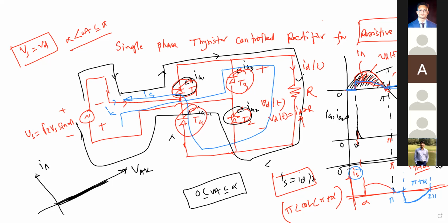Is the IS current sinusoidal or not? Not sinusoidal. Some portion is clipped. Is it sinusoidal or non-sinusoidal? Any other person other than IUT? Non-sinusoidal. If it is non-sinusoidal and repeating, then it will contain some harmonics. So will there be any even harmonics?